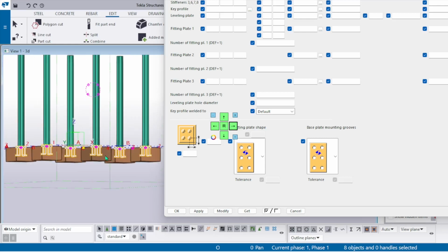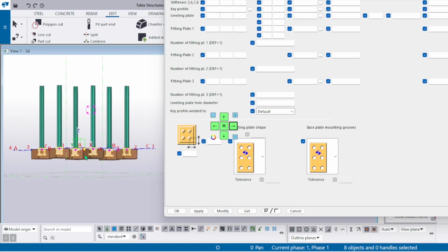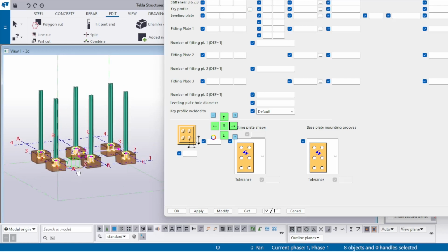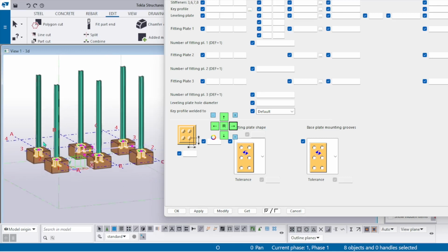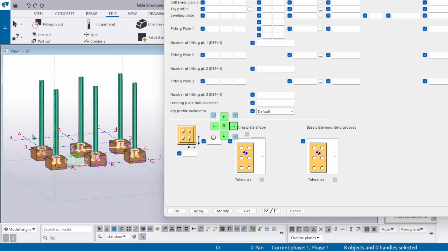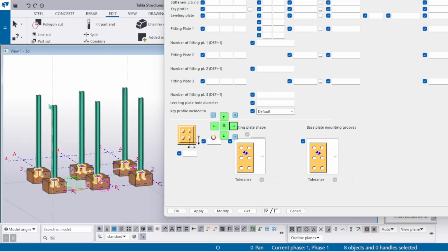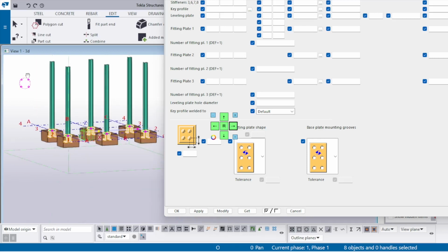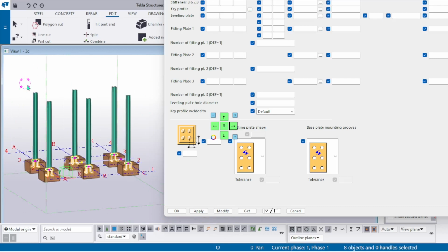And how I have done this: you always keep one finger on Control, then you can select with the mouse pointer. Drag the mouse pointer, using the middle mouse button to rotate. You can select from left to right and also from right to left.